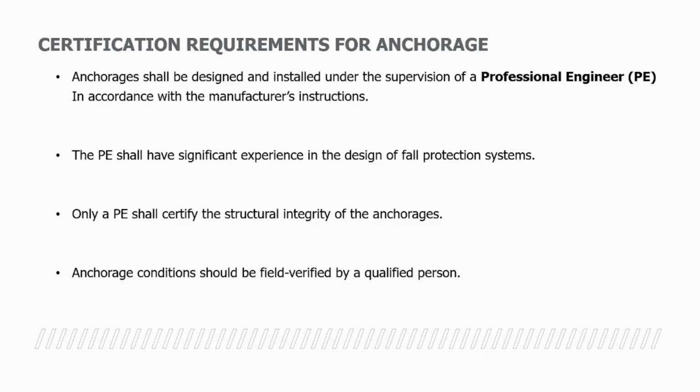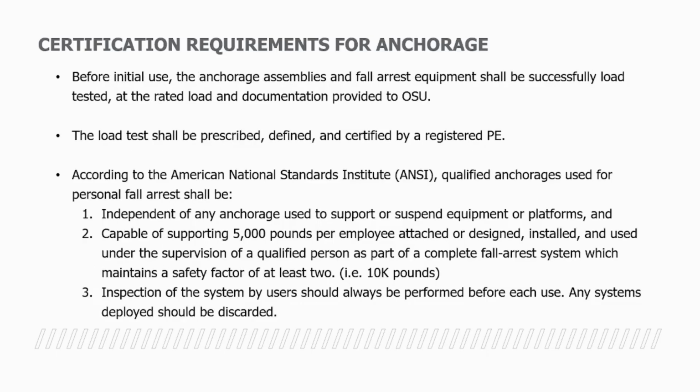When you go back and read into the standards, the anchorage point shall be designed and, once again, installed under the supervision of who? A professional engineer. Certification requirements for anchorage points include, before initial use, the anchorage assemblies and fall arrest equipment shall be successfully load tested at the rate, load, and documentation provided to Oklahoma State University Environmental Health and Safety. The load test shall be prescribed, defined, and certified by a professional registered engineer.